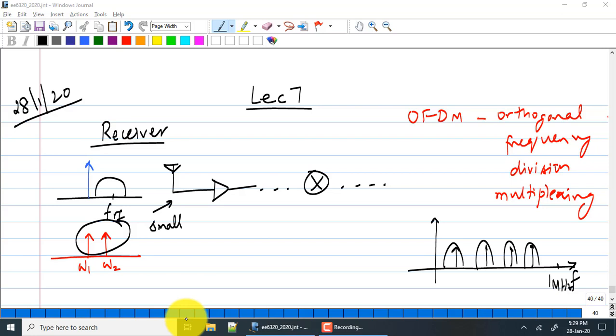You may have systems with different gains, different bandwidths, etc. But if you want to compare the noise performance, you compare the input referred noise sources. This is something like that. You figure out a standardized way of comparing the performance, and the way you do that is by characterizing the system with two equal sinusoids.